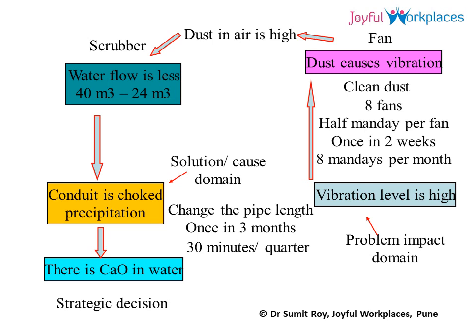And when I asked him whether he had observed any special observations, he said that yes, we have been measuring the vibration level, and the vibration level of late has gone very high. And the countermeasure that he takes is cleaning the dust from the FD fan. And he showed me a diagram depicting a graph where the vibration has been plotted against the days.